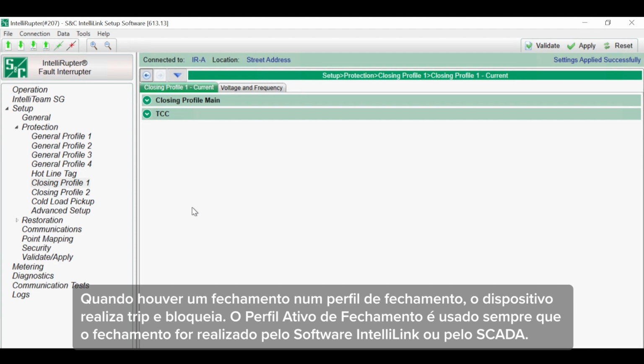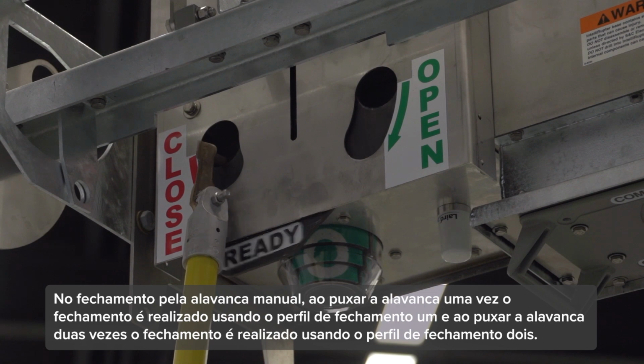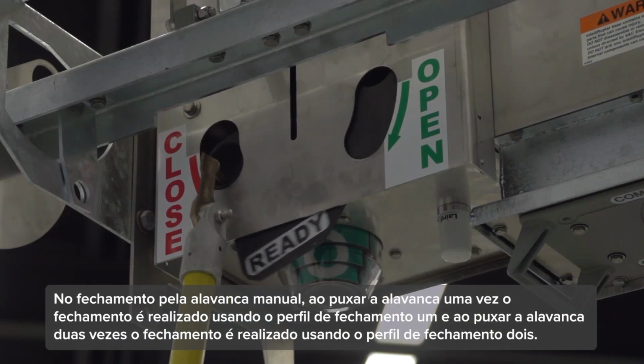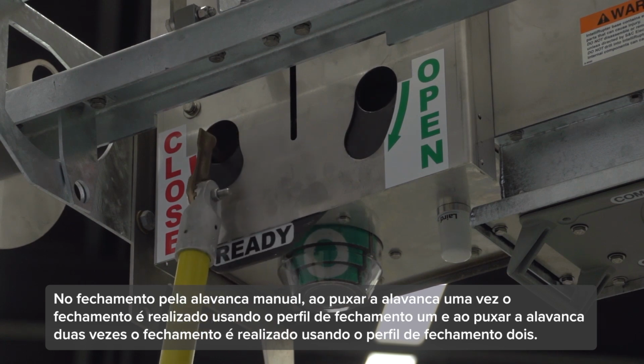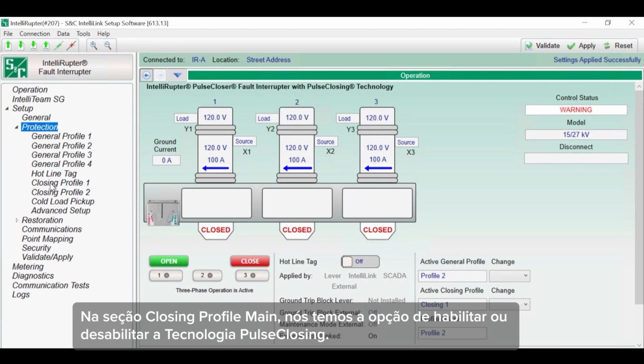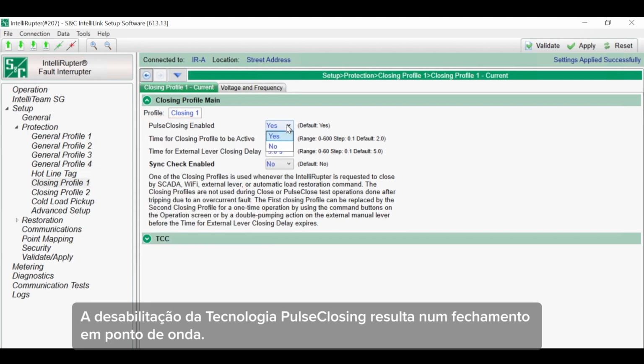The active closing profile is always used when closing from IntelliLink software or SCADA. When closing from the manual lever, pulling the lever once closes using Closing Profile 1, and pulling the lever twice closes using Closing Profile 2. In the Closing Profile Main section, we have the option to enable or disable pulse closing technology. Disabling pulse closing technology will result in a point-on wave closing.